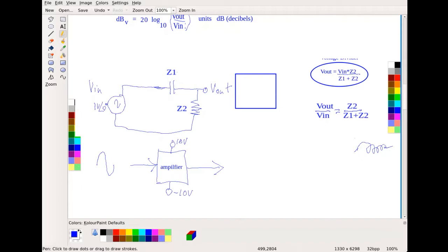Let's say this waveform coming in is a 2 volt peak system, and my amplifier is amplifying by a factor of 2. Then my output voltage has doubled, so it's going from 4 to -4.